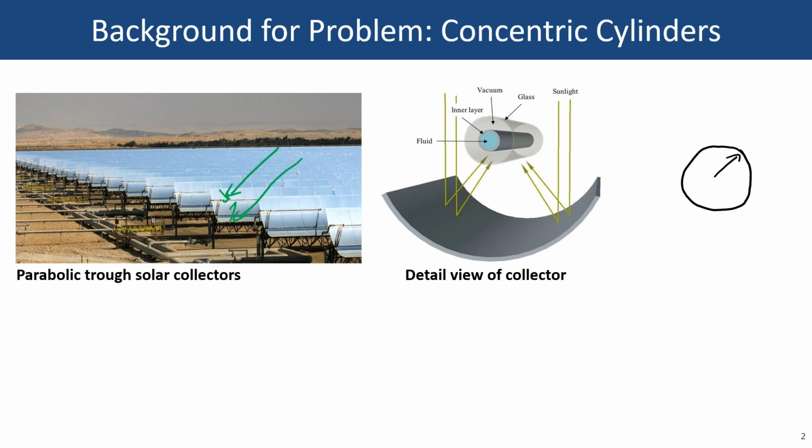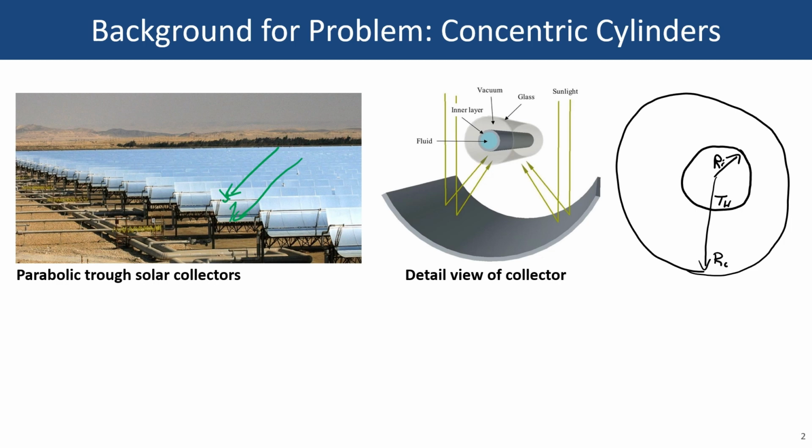We've got this inner tube that has radius Ri, and it has temperature TH. And then around that we have an outer tube, which let's pretend is concentric, with radius Ro and temperature TC. Between these two, if gravity is pointing downwards, then the air in that gap will be warmed up by the inner tube. So essentially you'll have a natural convection upwards, and the warm air that's rising towards the colder outer tube, you'd expect to start sinking downwards.